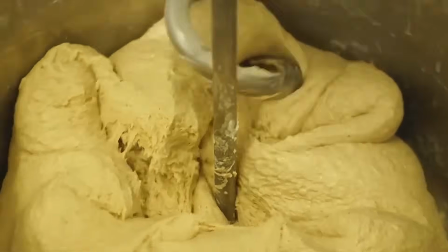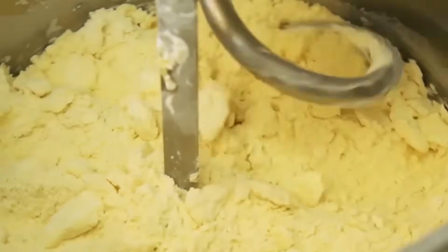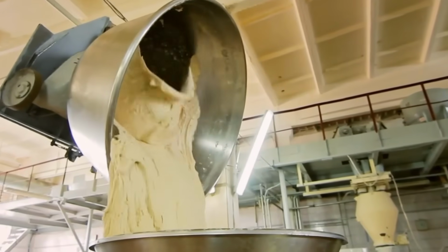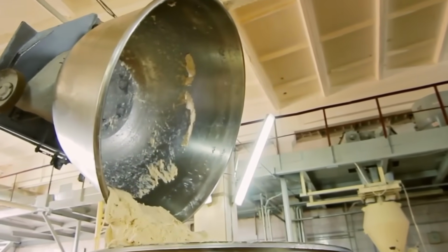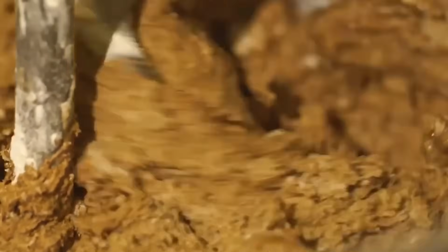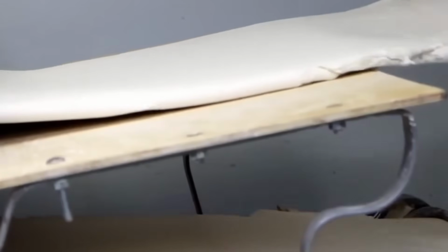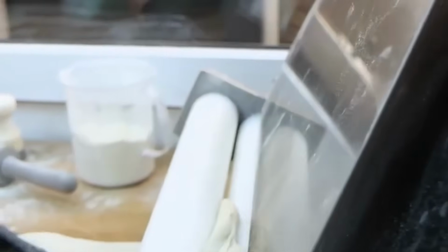All of these components are combined in large jacketed horizontal mixers or double sigma arm batch mixers. These mixers are chosen for their ability to handle heavy, cohesive doughs while still ensuring thorough dispersion. Inside the mixer, paddles or blades knead the dough continuously, folding and stretching it to develop a uniform texture. The mixer operates under a specific time and speed profile, starting slow to incorporate the dry and wet components, then increasing speed to blend, then finishing with a gentle knead to avoid overworking the dough. The goal here is a dough that's soft but not sticky, cohesive but not tough.